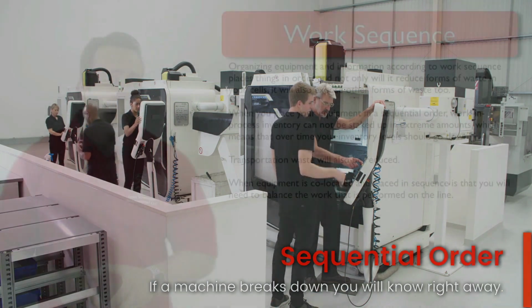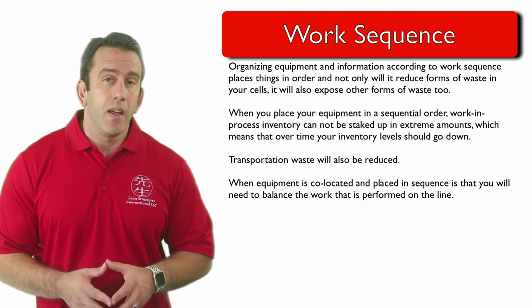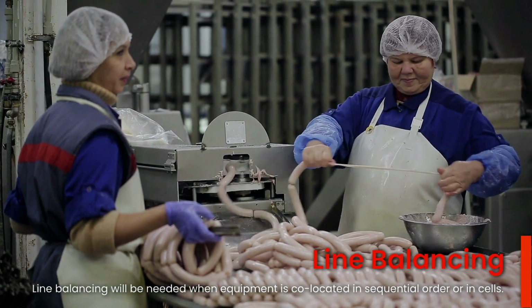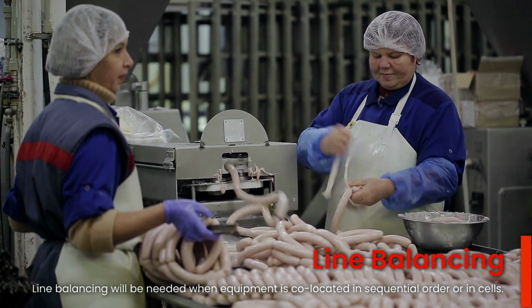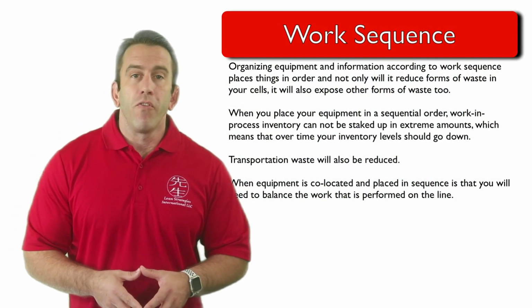Another opportunity that will become obvious when equipment is co-located and placed in sequence is that you will need to balance the work that is performed on the line. This is referred to as line balancing. As you can tell, the benefits of moving from a functional-based layout far exceed any challenges that you might be presented with. Lead times will go down, floor space will be freed up, and WIP inventory will be reduced, which ultimately frees up cash flow for your organization.